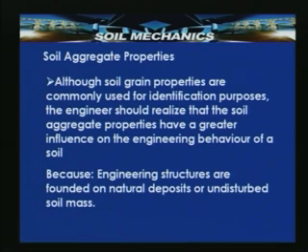Out of soil grain properties and soil aggregate properties, soil grain properties are widely used. So, although soil grain properties are commonly used for identification purposes, the engineer should realize that the soil aggregate properties have a greater influence on the engineering behavior of the soil, because most of the engineering structures are founded on the natural deposits or undisturbed soil mass.